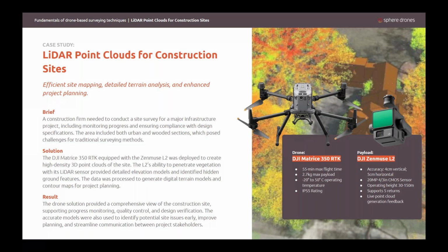That one has a 360-degree scanner, really tight precision and accuracy, really good vegetation penetration, and a 61 megapixel integrated camera, or you can use a dual oblique camera as well. So some really nice options are available on the market at the moment.